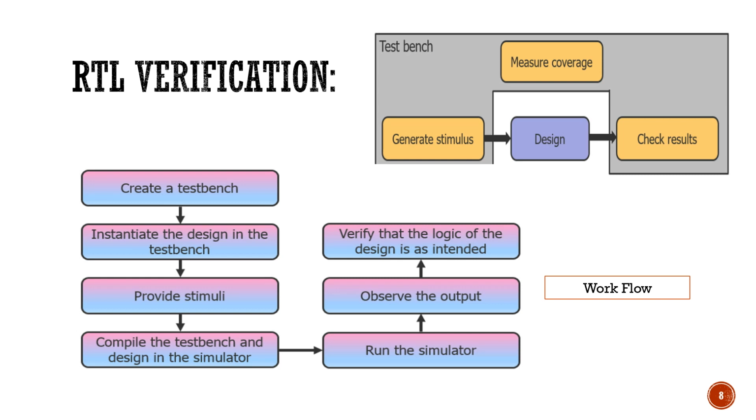So we are going to apply test input vectors for the device under test that we have designed, and we are going to check the results and measure how much fault is going to be created in our design. To start with is the creation of a test bench. Suppose I want to write the code for a test bench of a half adder, you need to do an instance.